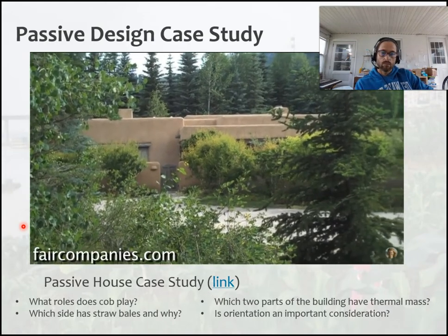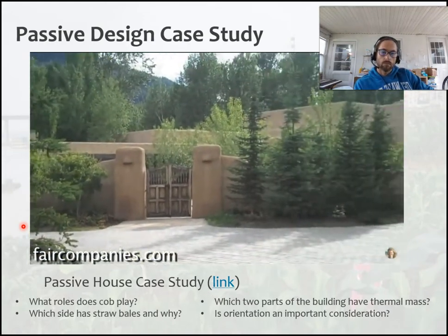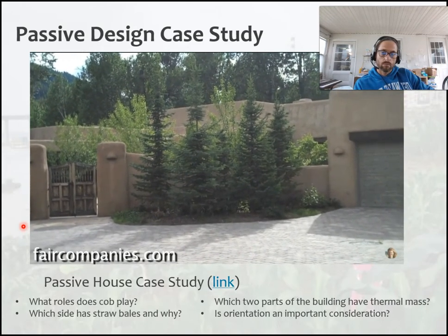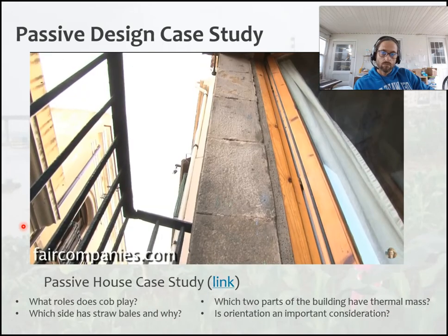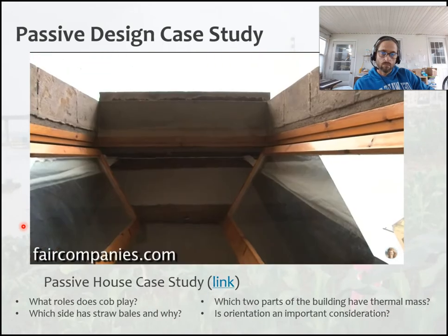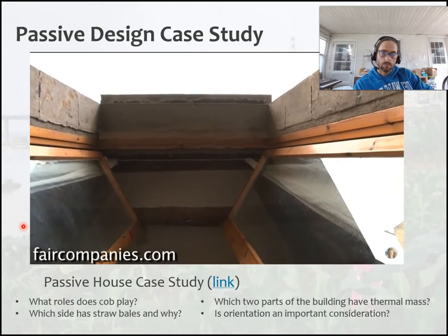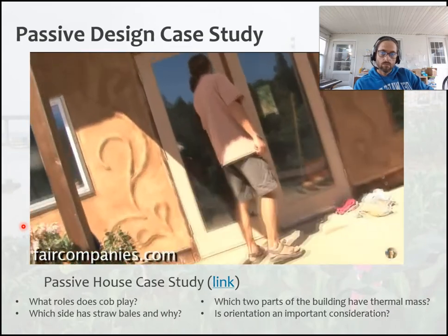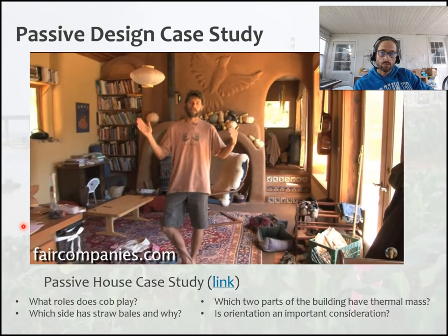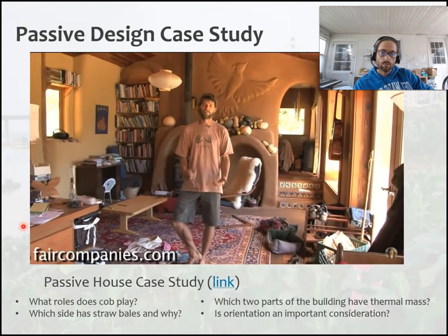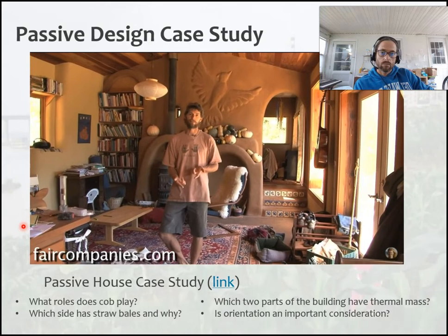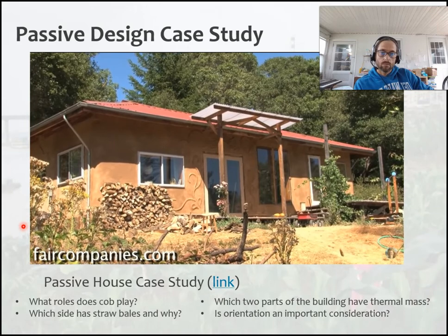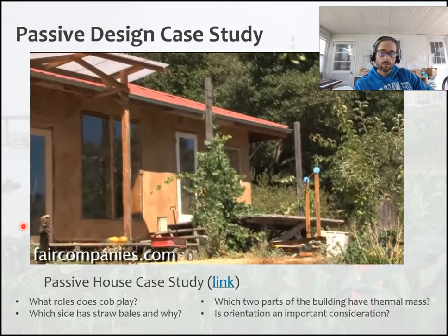Historically, if you look at hot desert architecture anywhere in the world, what you see is really thick masonry walls made out of earth usually, or stone. Those walls hold the coolness from the nighttime and very, very slowly heat up during the day. The way we do it here, at night we open up all the windows and let the cool night air come through the house, and that discharges any heat that's been stored up in the thermal mass during the hot day. And then in the morning we close up all the windows and just keep that coolness locked inside the building.